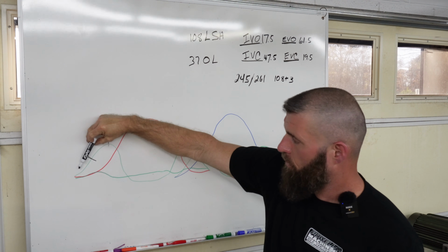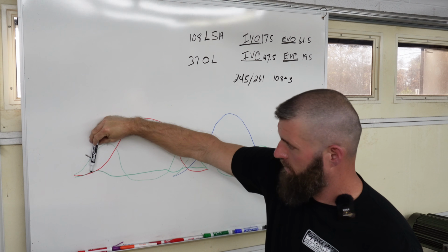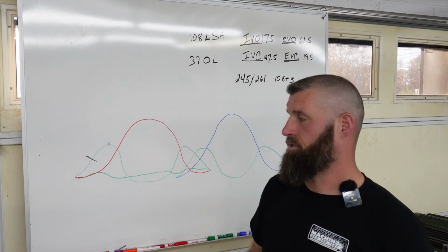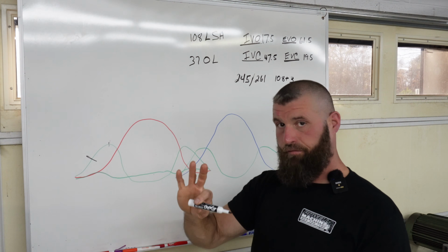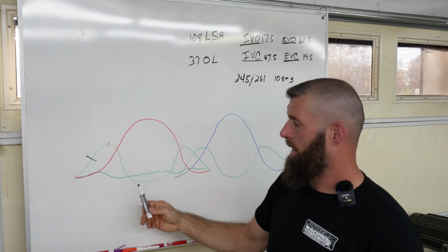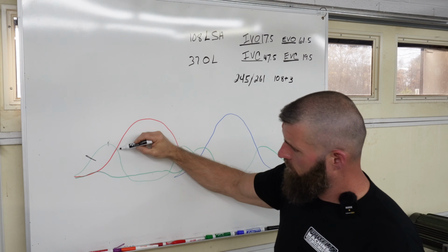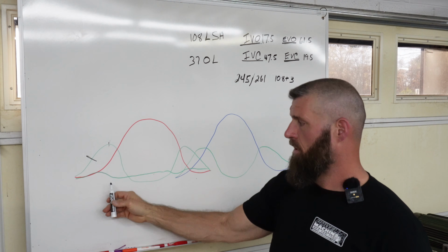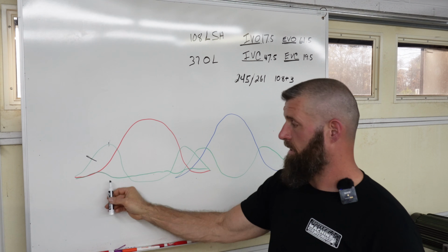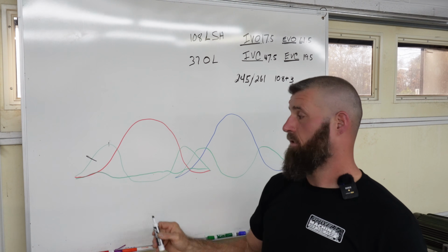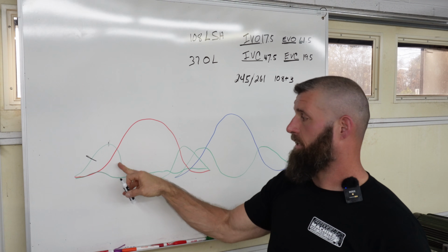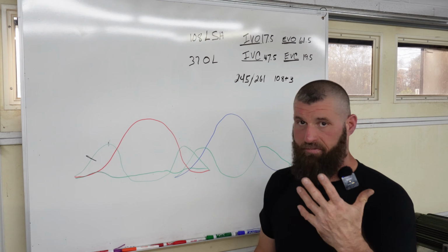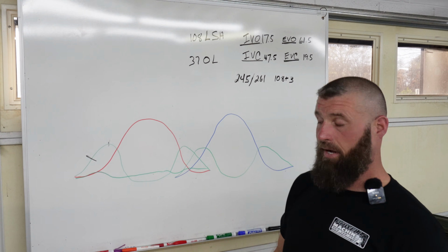If you make the hydraulic intensity less and less, this angle gets steeper and steeper. And conversely, on this side, the angle of the decel of the acceleration curve ends up being negative jerk, because jerk is the rate of change of acceleration. That's where the valve train gets in trouble, right?